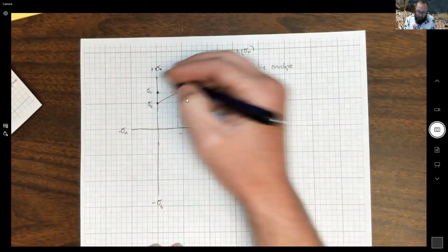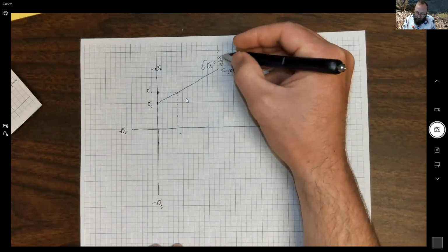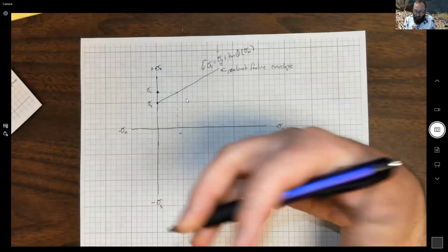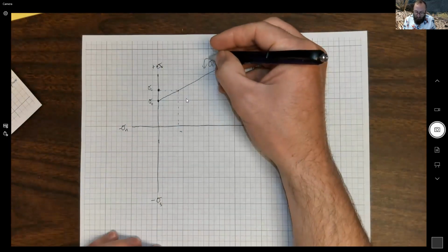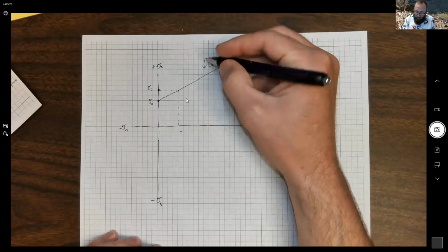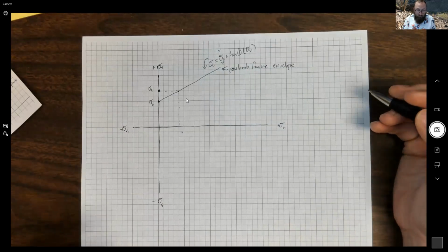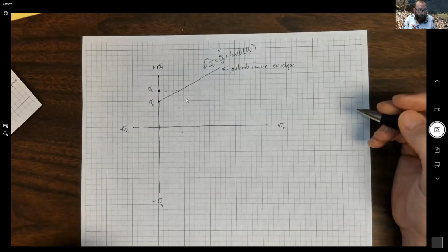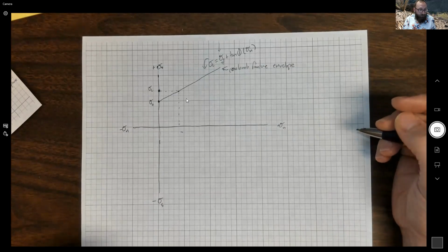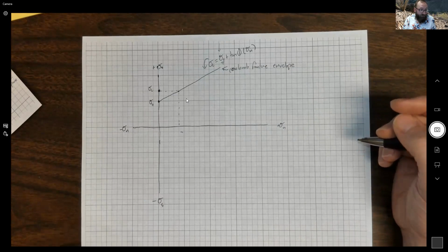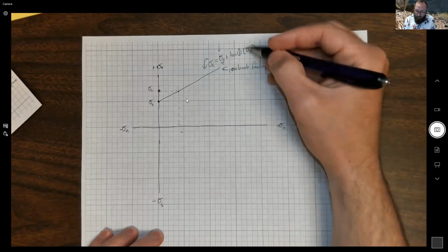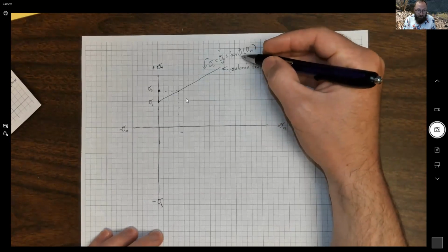So the rest of the critical shear stress that we have to overcome, to get this side of the equation larger than this side and cause failure and a fault to form, is basically the resistance to triggering movement on the fracture. This component is what we label tan phi sigma n.